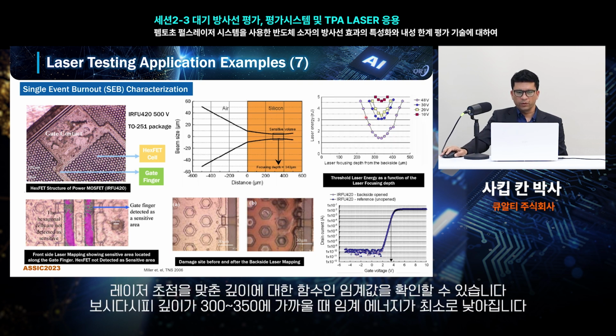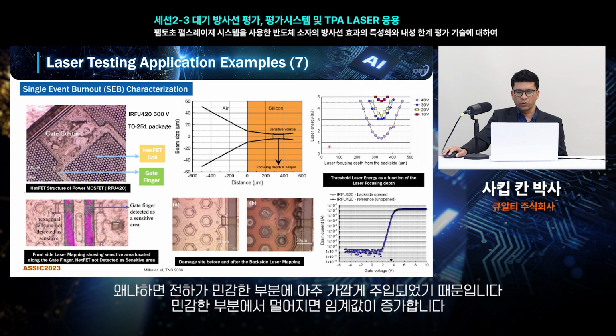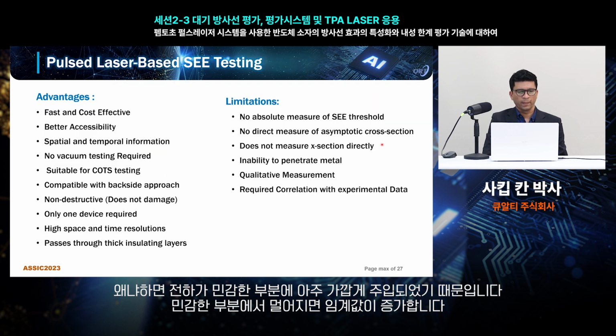And here you can also see the threshold energy as a function of laser focusing depth. When the depth is close to 300, 350, the threshold energy is minimum because the charge is injected very, very close to the sensitive volume. As we move away from the sensitive volume, the threshold increases.